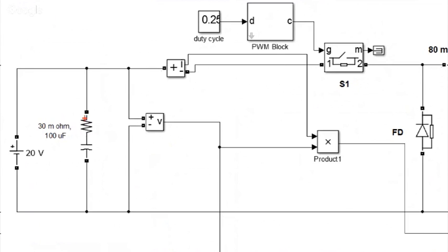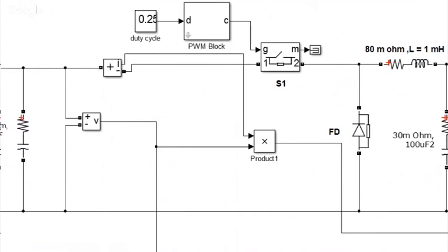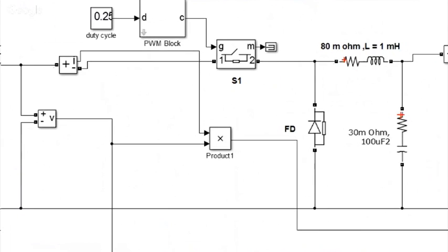So here, DC voltage you can see I gave 12 volts. Then after that, at both the input end and output end, we put a capacitor. But I told you with that even the ESR has to be put, that is the equivalent series resistance. So that value was measured and put. We had an ammeter and voltmeter just for measuring purposes. Here you have the switch. I already told you in a buck converter, a switch is there, an inductor and a diode. So those are the three components you can see.